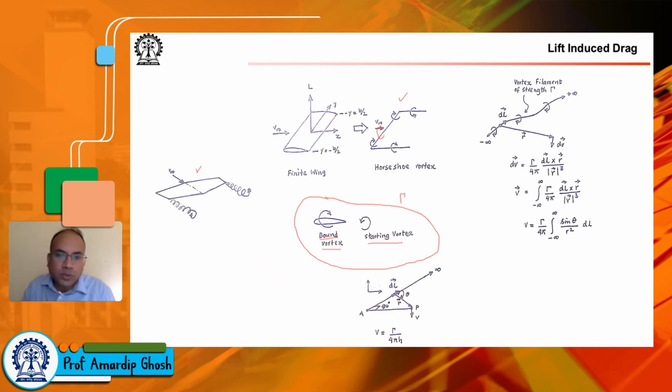But nonetheless, we use that argument to say that the moment you have a starting vortex, you generate a bound vortex. That was from the Kelvin circulation theorem, and then also from the Kutta condition, which is observed experimentally, we said that the strength of the bound vortex will be such that it will make the flow leave the trailing edge smoothly. So that is the strength of the bound vortex we have here. The strength of the horseshoe vortex, I will hold on to that for the subsequent discussions.